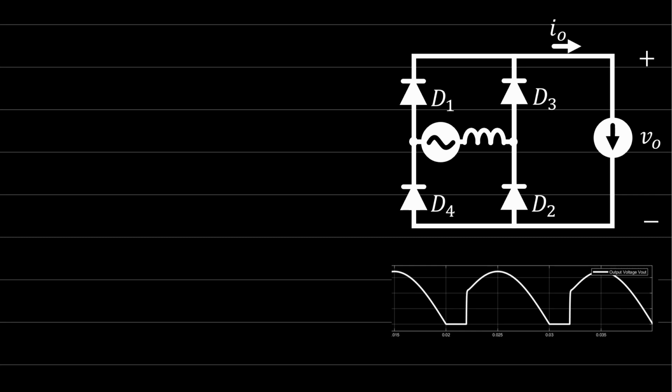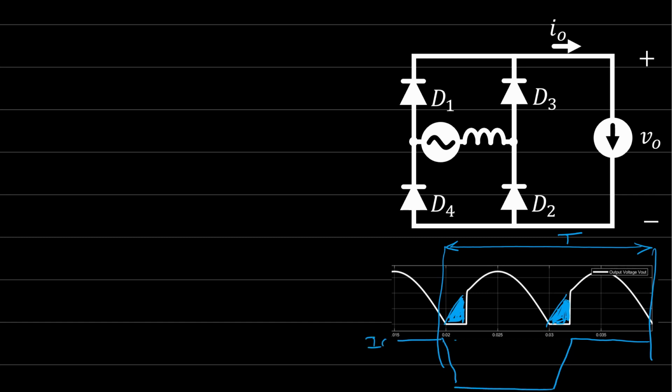For the single phase full wave rectifier, we can say easily that this portion is taken or eaten during the commutation. Here we said the input current is changing from minus I out to plus I out. So you can see that here the input current is changing from here, and this is minus I out. Let's say that this is 0, for example, and this is Tz.